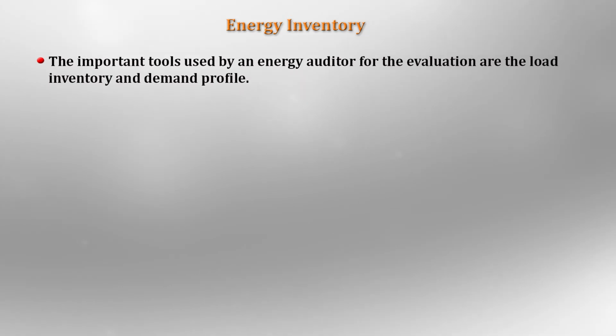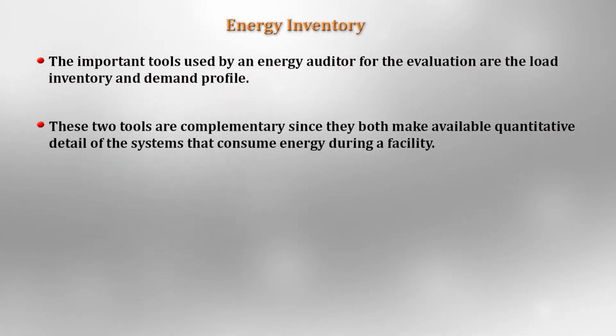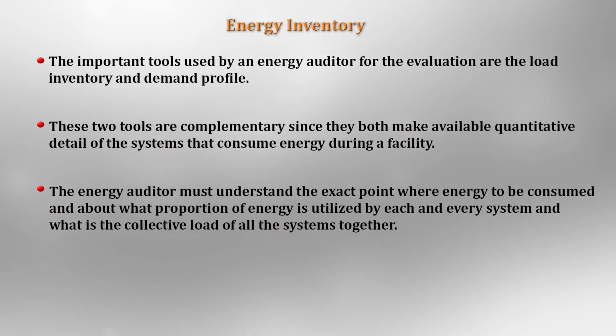The important tools used by an energy auditor for the evaluation are the load inventory and demand profile. These two tools are complementary since they both make available quantitative detail of the systems that consume energy in a facility. The energy auditor must understand the exact point where energy is consumed, about what proportion of energy is utilized by each and every system, and what is the collective load of all the systems together.